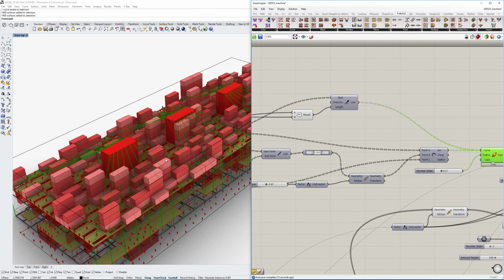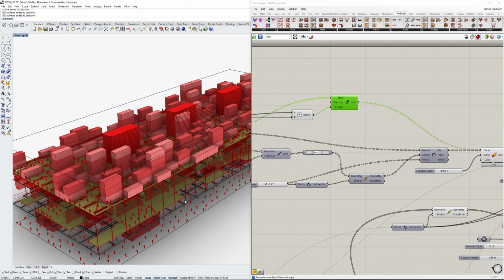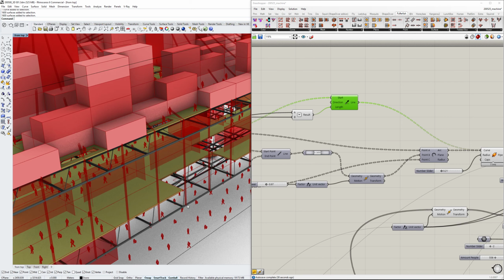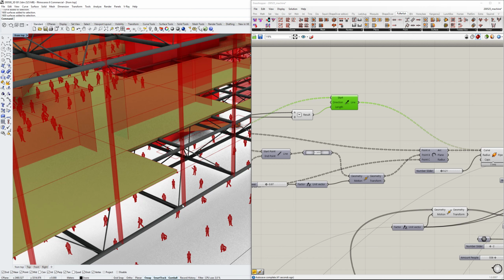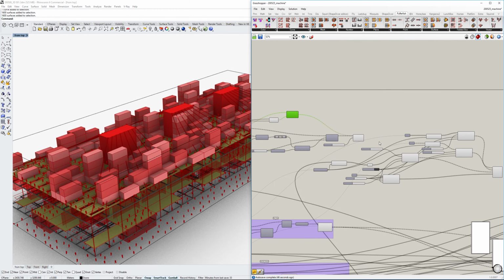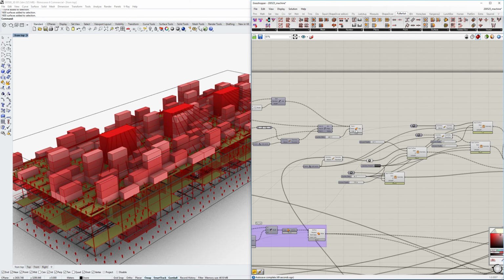And then those go on this point that we defined before, and the endpoint C is a new point from the new number slider, like the SDL, the direction line, which I think is this one here, yeah. And it creates a downwards line that will be connected to the last point here from our structure on the second floor, so they get connected together as well. And then obviously the pipe command.